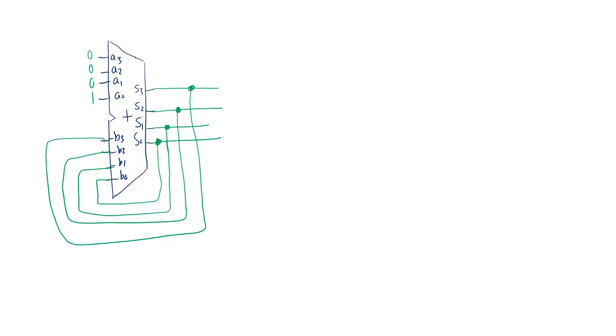So I start from, let's say I reset this to 0, 0, 0, 0. The next output is going to be 0, 0, 0, 1, and then 0, 0, 1, 0, all the way to 1, 1, 1, 1. And then let's say I don't care too much about the overflow. I'm going to put an overflow detector that, whenever you get 1, 1, 1, 1, whenever all of the outputs are 1, resets this adder to 0, 0, 0, 0. Okay? So don't worry too much about the overflow detector.